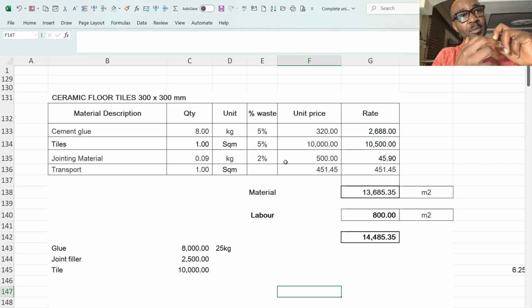It has gaps in between that are used to scoop off the excesses you have placed on the floor, to give you an even level before you begin to place. Those notches range, I think, between 3 to 10 mm deep. So the thickness of the adhesive depends on the type of trowel you are going to use to lay the tiles.